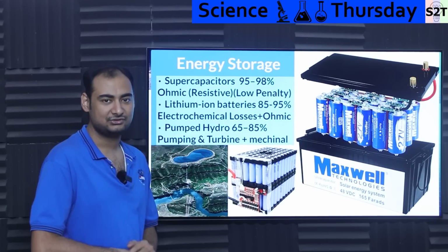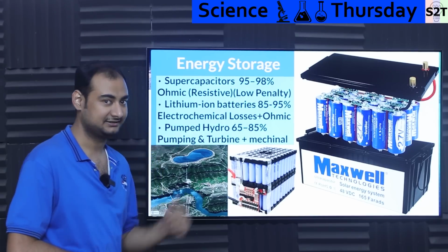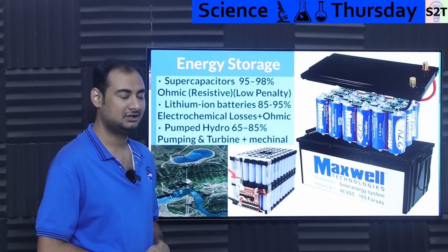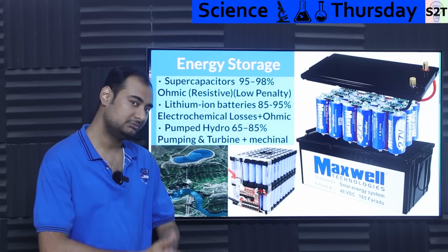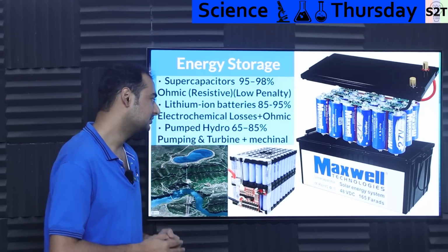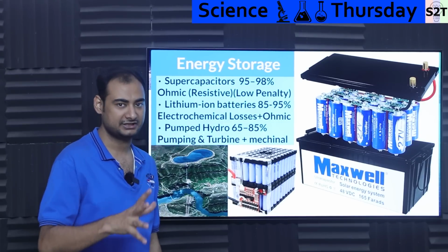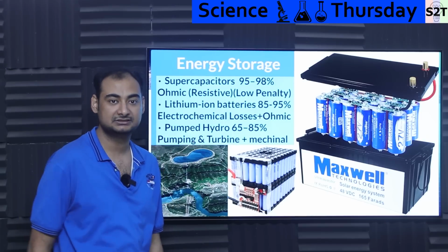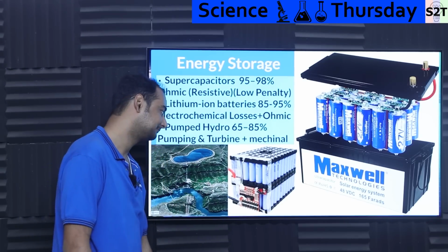So if somebody comes to you and says, we're going to have pumped hydro that's going to be 95% efficient, run. It's a lie. Again, the laws of physics are like, nah, bro. 80% should be doable. 85, you're pushing it in terms of cost, but it should be doable. So assume 80 to be the baseline. So this is just the energy storage context, and that's why these things have such different characteristics, because the laws that are affecting them are different.